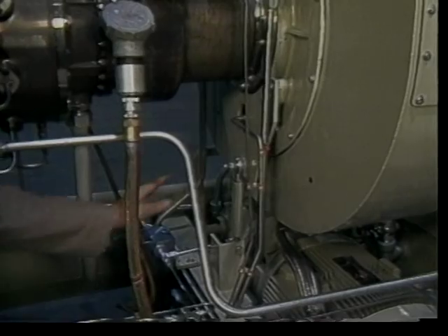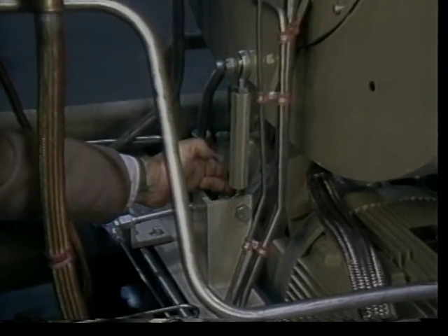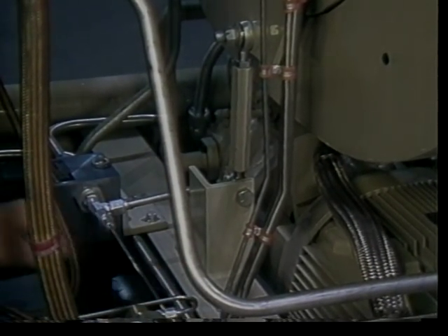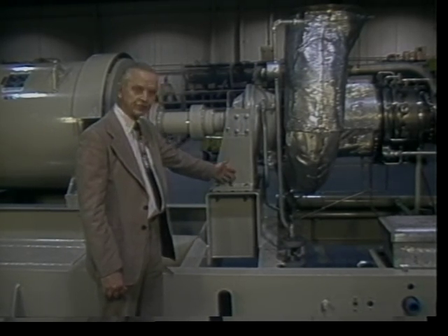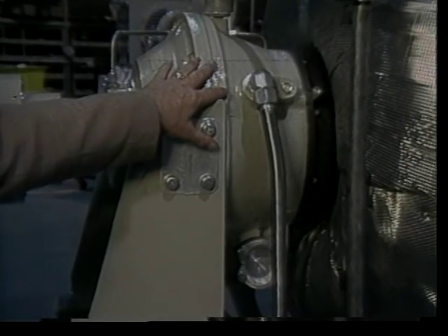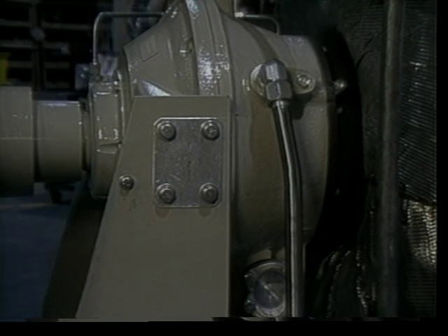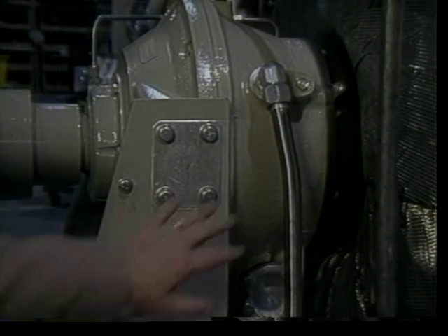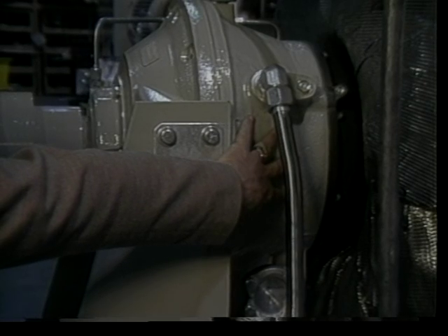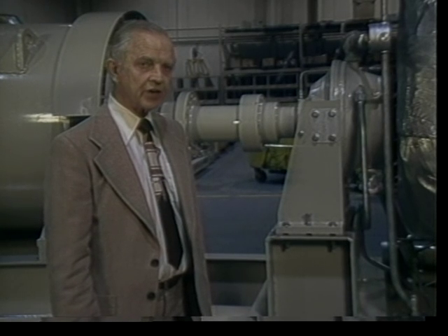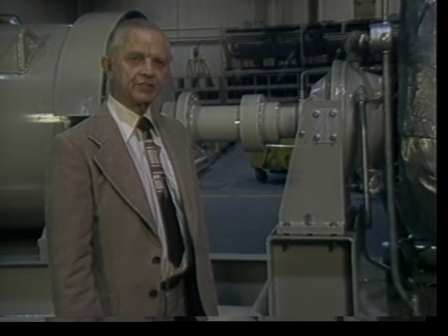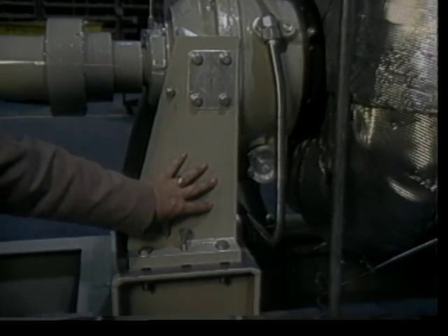The engine is supported on the forward end by a bracket attached to the skid base frame and by the output reduction drive assembly support at the aft end of the engine. The two-stage reduction gearbox in the output reduction drive assembly reduces drive speed from the engine to the generator. The first stage reduces the speed from 22,300 RPM to 6,000 RPM, and the second stage reduces from 6,000 to 1,800 RPM for 60 Hertz and 1,500 RPM for 50 Hertz. The assembly is mounted on the skid base frame by a trunnion-type mount.